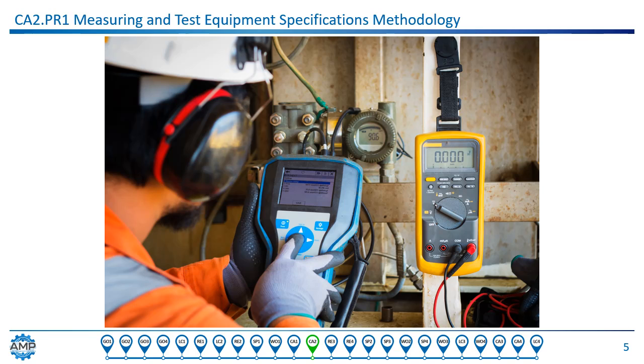Since not meeting this parameter will shut us down, we want to be certain we can control the process within this range. If a temperature control loop is used that has a tolerance of 0.1 degree and we set it to control at 95 degrees, it's obvious that the instrument is suitable to keep temperature where we want it. We expect the process to be controlled between 94.9 and 95.1 degrees.